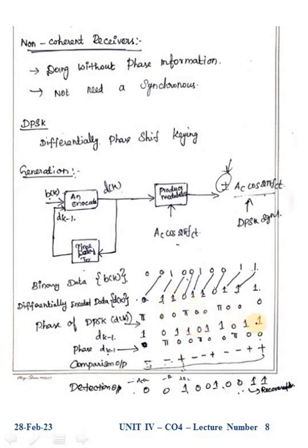In this way you write the outcome. Then the phase of dk minus 1: as I said earlier, if it is 1, then 0, and 0 means pi. That is, if the outcome is 1 or plus 1, there is no phase shift. If it is 0, then the phase shift is considered as 180 degrees.